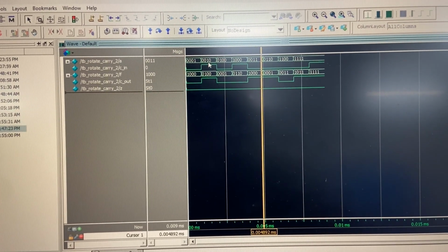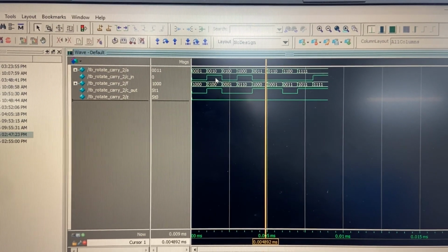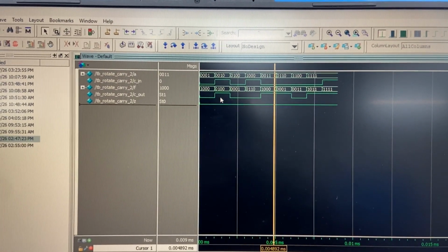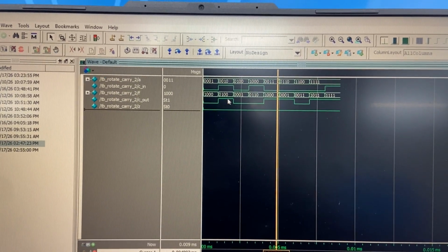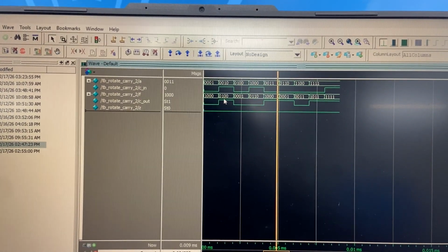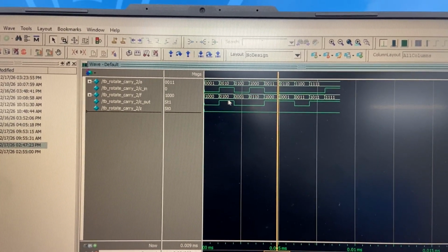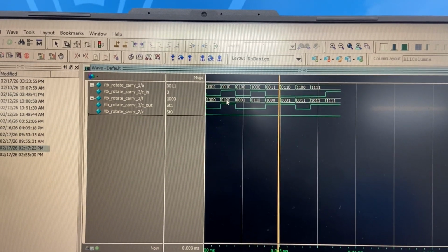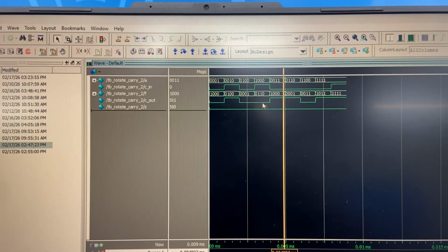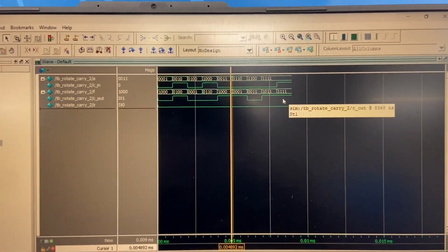But if we have a 0010 right here, if it shifts right 2, what ends up happening to this piece of information is it goes into the carry out. So it's in the carry bit. And then we also had a carry in, where that is going from where the carry out bit would be held, shifted right 2 into the 3rd position of the F output. And then more examples represent that down here.